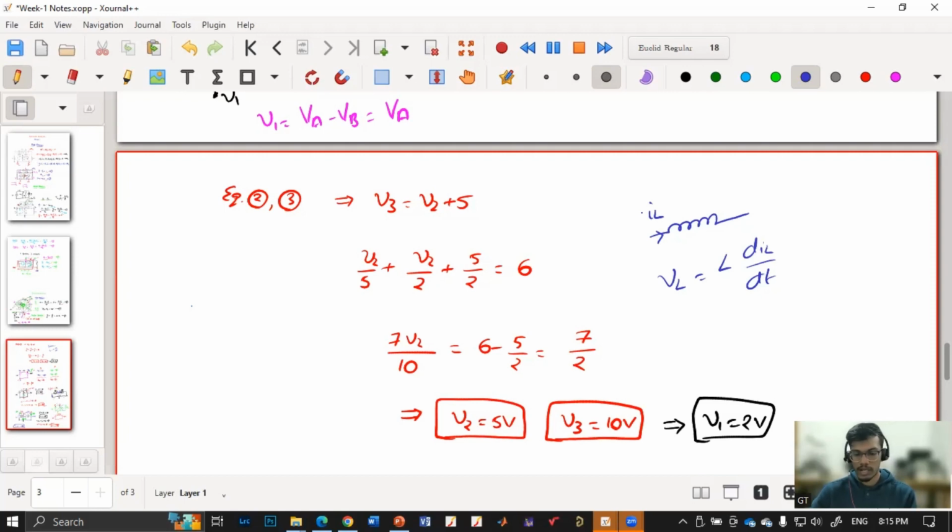But you can think from the capacitor point of view. A capacitor can be a voltage source, right? When it is fully charged, it becomes open and it is at a particular voltage. Similarly, these two are vice versa. It is the capacitor voltage that cannot be changed immediately, and similarly, it is the inductor current that cannot be changed immediately. This is one set of examples.